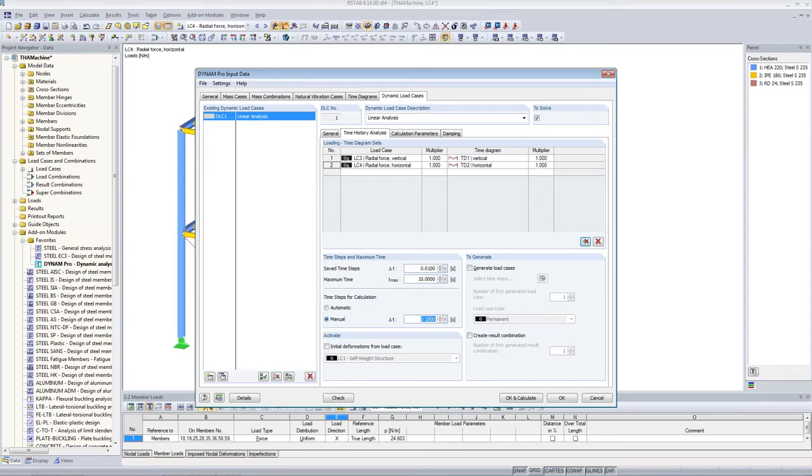And this is basically just the formula that you have seen in the slides earlier, 1/20 f frequency. And when I calculate this, I end up with this time step. It's even smaller because I have defined my save time step this way. The save time step is just for a smooth curve later on. So if you want to have a smooth graph, a time course graph, then you have to reduce the time steps here. If you do not need this, then you can increase the time steps because this saves, of course, memory and calculation time, because also the saving takes some time.